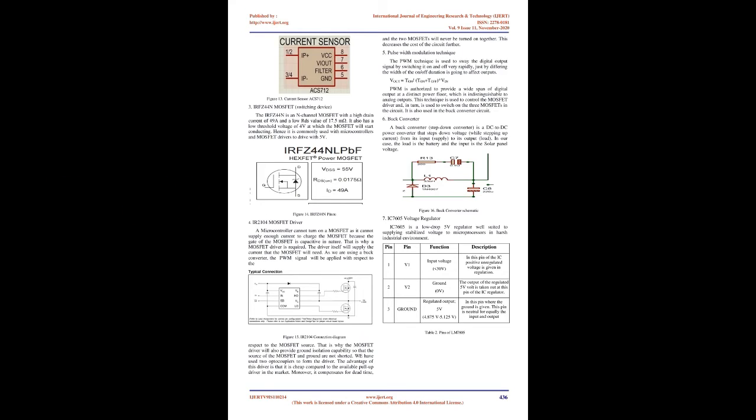The difference between the series regulator and the PWM regulator is the PWM of the transistor. When the modulation width is at 100% or 0%, the regulator is essentially a series regulator. It is that modulation width variation that allows the PWM regulator to create a constant voltage to the battery as opposed to the on/off of the series regulator.